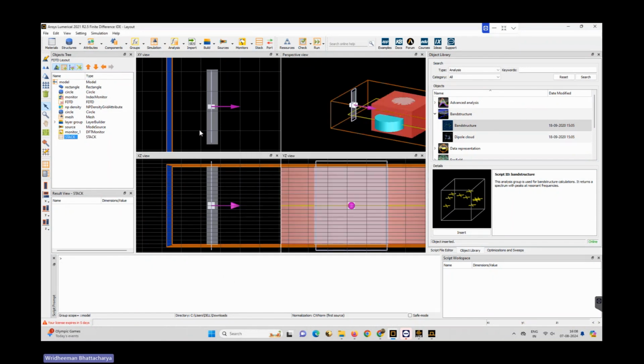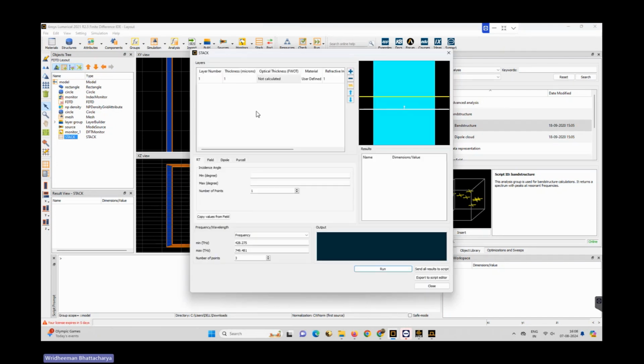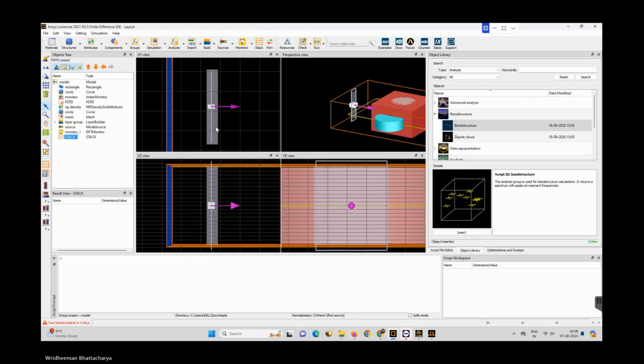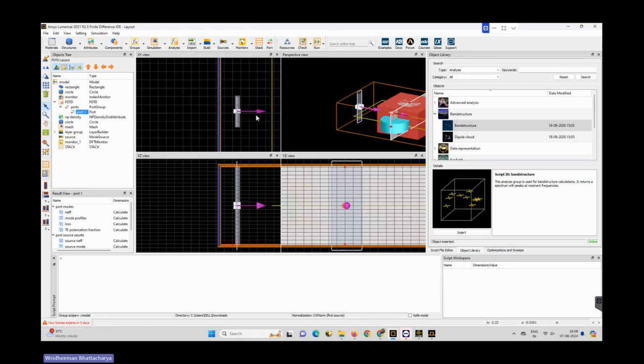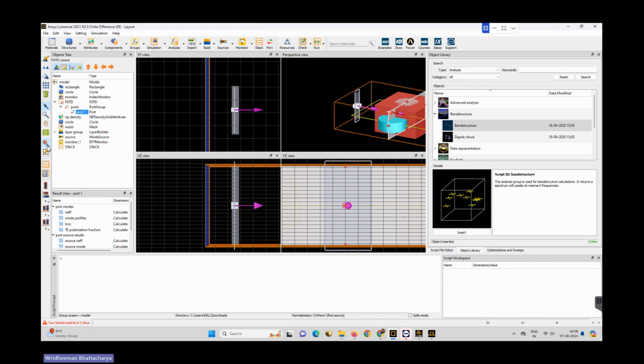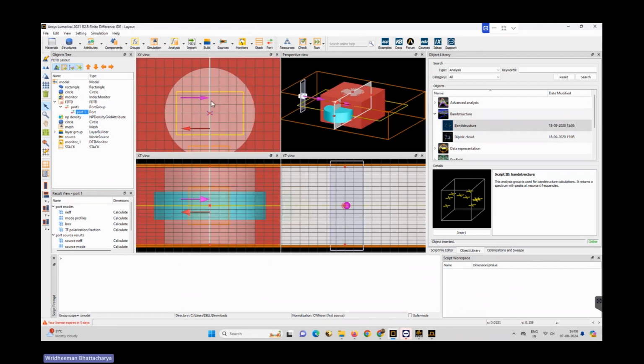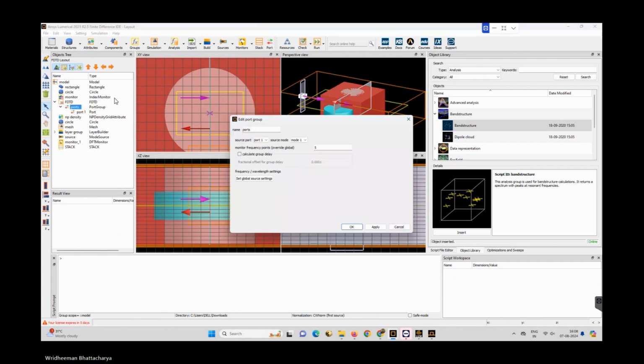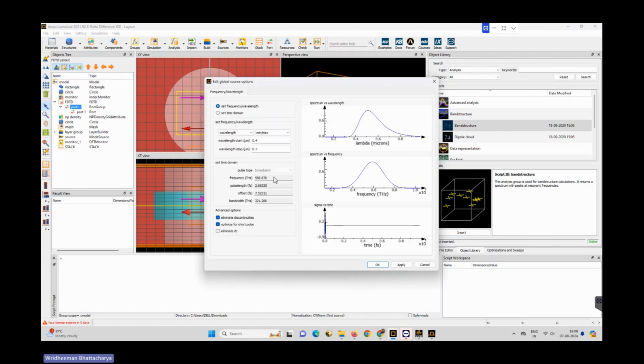This is the stack part, right? Stack is similarly the layers which will be built upon. So you could just set layer thickness and materials. One by one you could just increase. Many features are already there here. Similarly, ports are generally just ports. Ports generally act as both sources and monitors, right? In ports, we give this mode 1 and frequency. We give the set global source settings.